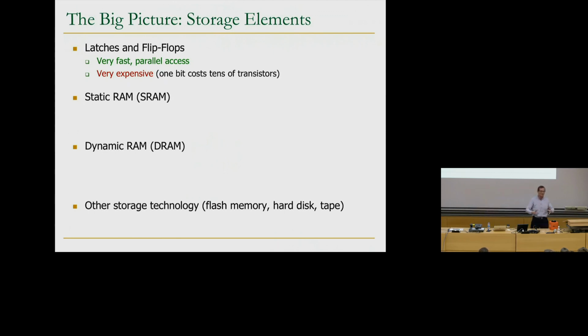Well, we'll keep adding logic gates, but you know that logic gates are composed of transistors. A NAND gate is 4 transistors, remember. Actually, the register file, the D flip-flop based register file that we're going to construct for a single cell will have, well, I guess, quite a few NAND gates. We'll see later. Static SRAM, what I showed you earlier, it's relatively fast, not as fast as this one. It stores only 1 data word at a time, but it's expensive. 1 bit costs 6+ transistors, but it's not as expensive here. So it's slower and less expensive.